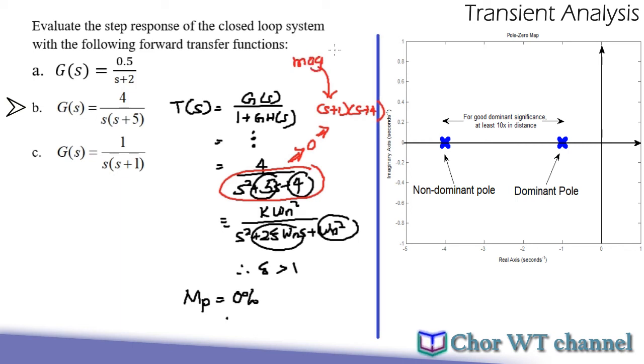Magnitude is the lowest one, and we can determine that this is the dominant. So the dominant roots will be the one controlling the system's transient because it stays in the system longer, and s plus 1, so this implies that my tau is equal to 1.